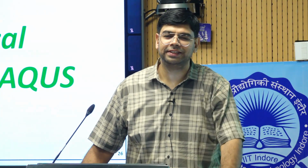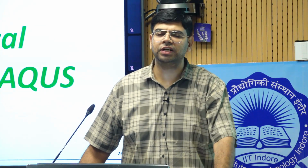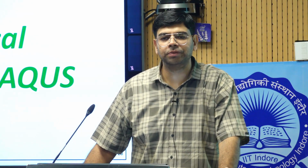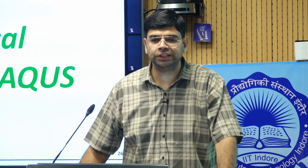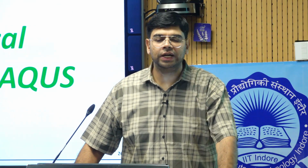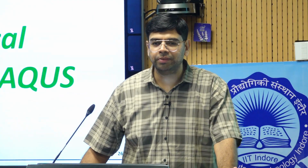Now, in the analytical model, specifically for the DMS, we have considered simple homogeneous deformation. But in actual practice, when this type of actuator is used in practical applications, it undergoes inhomogeneous deformation. I hope all of you have understood homogeneous and inhomogeneous. If you want to incorporate that, you cannot do it in the analytical formulation. It makes the equation very complicated, and it cannot be solved easily by the analytical method that we have considered.